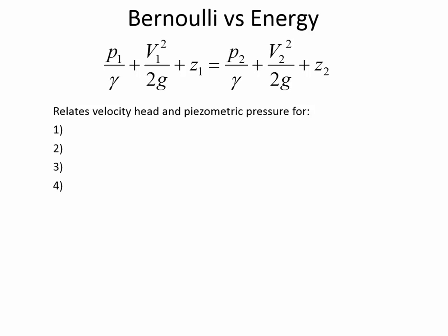Bernoulli's equation we'd sometimes use for a nozzle. Here's our nozzle, and Bernoulli's equation is the kind of thing that tells us when you've got a slow velocity, then it goes to a fast velocity, how does the pressure change from location 1 to location 2? So what we said with the streamline thing is that the water is flowing through here, and it sort of follows a typical pattern, and you can only apply it along the same streamline. Otherwise, Bernoulli's equation isn't valid.